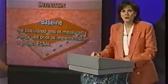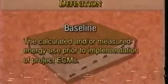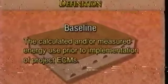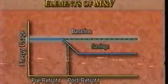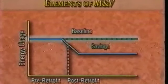Okay. So M&V procedures are designed to be flexible in evaluating energy savings and contain three elements: baseline, adjusted baseline, and measured performance. First, let's define these terms, starting with baseline. The baseline is the energy use prior to implementation of ECMs. It can be either measured or calculated. The baseline will be used throughout the contract. It contains all the relevant performance information.